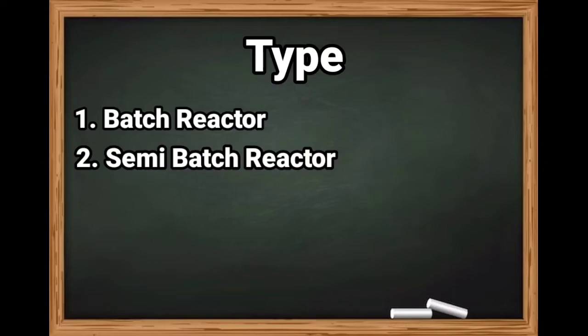And then the second one, there is the semi-batch reactor. A semi-batch reactor is operated with both continuous and batch inputs and outputs. A fermenter, for example, is loaded with a batch of medium and microbes which constantly produce carbon dioxide that must be removed continuously. Similarly, reacting a gas with a liquid is usually difficult because a large volume of gas is required to react with an equal mass of liquid. To overcome this problem, a continuous feed of gas can be bubbled throughout a batch of liquid.